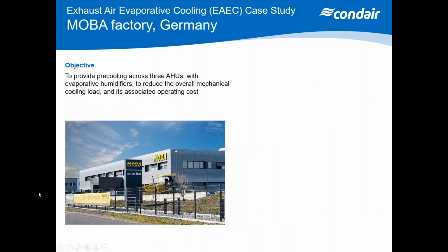So this case study that utilizes exhaust air evaporative cooling is the Mover factory in Germany, and the objective was to provide pre-cooling across 3 air handling units with evaporative humidifiers to reduce the overall mechanical cooling load and its associated operating costs.